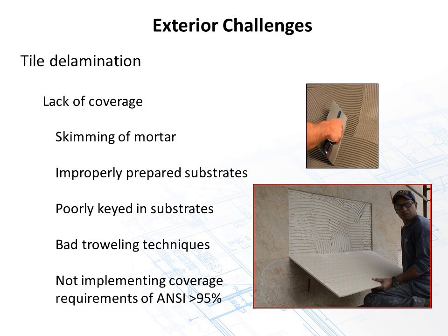Lack of coverage, poor troweling techniques, skimming over the mortar, as I talked about earlier, because maybe it's open to the wind. Properly prepared substrates are critical. You should be 1/8 of an inch in 10 feet for anything over 15 inches on one edge.